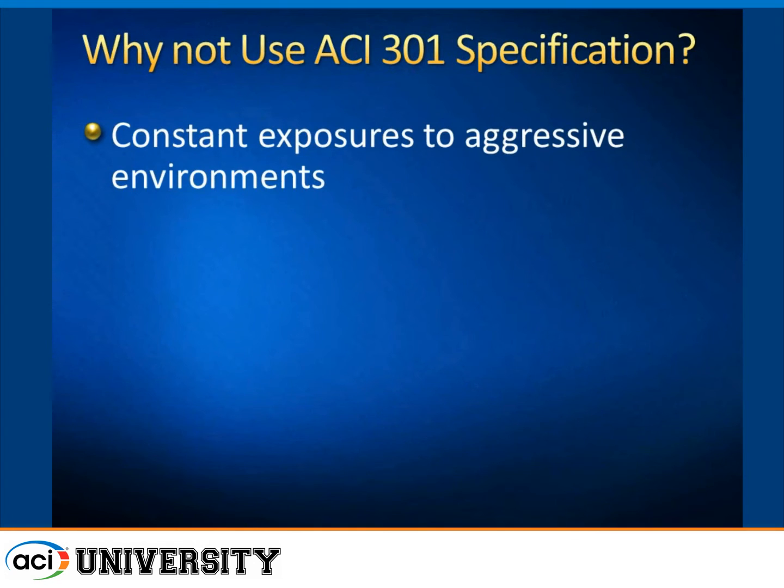We also have constant exposure to aggressive environments. We have certainly liquid, and then some people say, well, water, that's not aggressive. Well, actually wetting and drying in the water-air interface can be very aggressive towards the performance of the concrete. We also have a lot of potable water that, as you're making the potable water, there's treatment chemicals that can have a lot of impact in terms of either attacking concrete or potentially causing corrosion. So we have specific requirements for containing liquids. And then the chemicals, the treatment chemicals. Also, we can deal with wastewater treatment that is aggressive just by the wastewater.